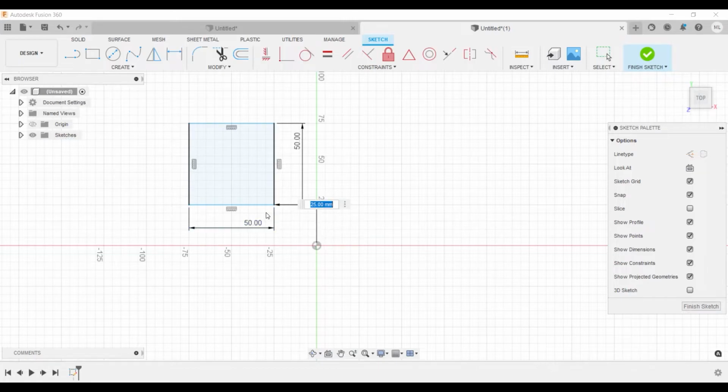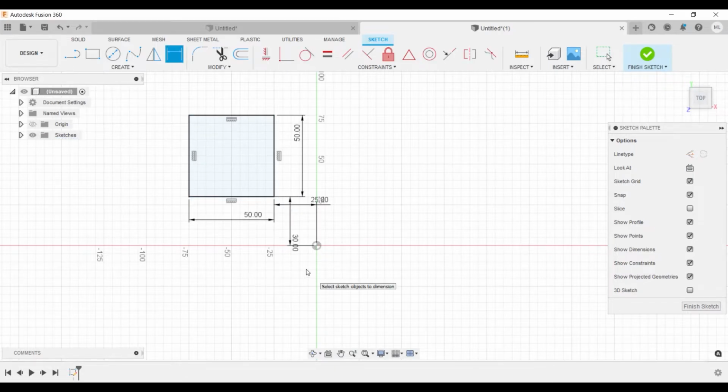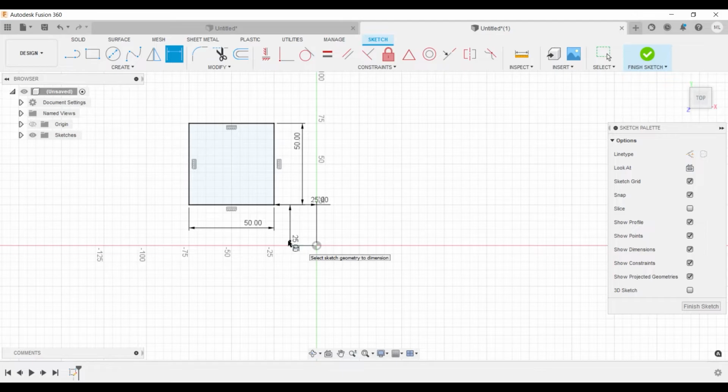You can't move around a fully constrained sketch, so constraining parts of the sketch, or the complete sketch, is a method for locking up the design. Watch as I hit D, the hotkey for dimension, and add dimensions. As I put my dimensions out there, parts of the sketch become constrained. I've set rules for the sketch, and because of those rules, I can't move those parts. Those lines are black. Not fully constrained lines remain blue in Autodesk Fusion 360.